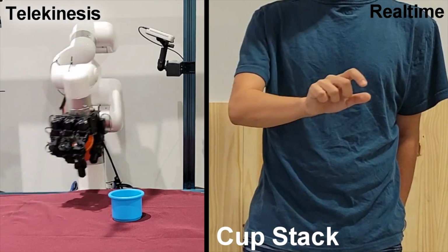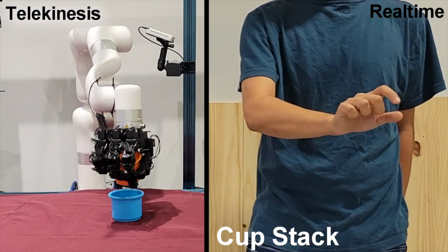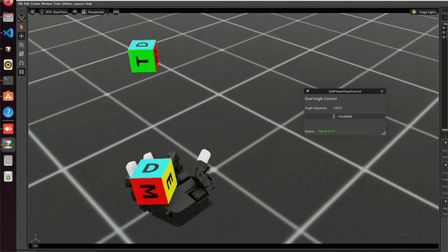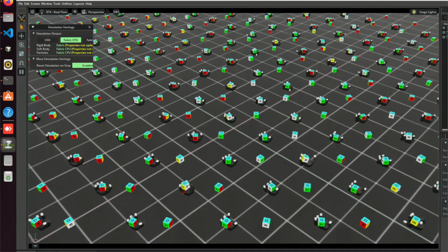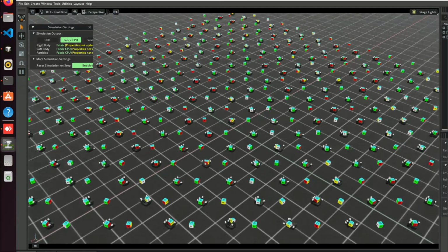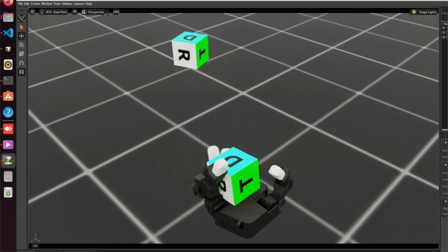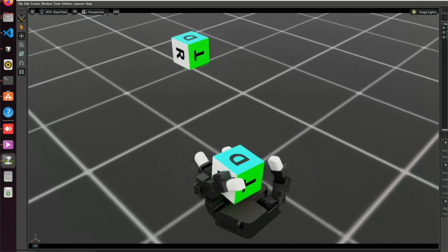For simulating the Leap hand, we relied on NVIDIA's Isaac Lab and the GPU-accelerated physics, which support rich manipulation dynamics and realistic modeling for both friction and compliance. We created an environment to batch many parallel simulations for massively increased RL throughput. In training, we implemented customized curricula and iteratively improved reward functions. We also improved the deployment of the inference model in order to test custom control inputs.